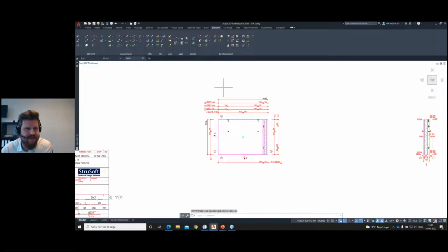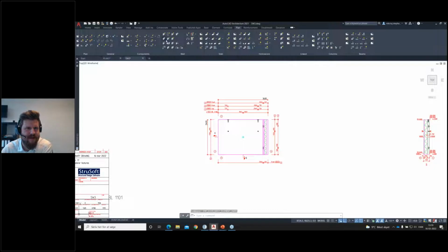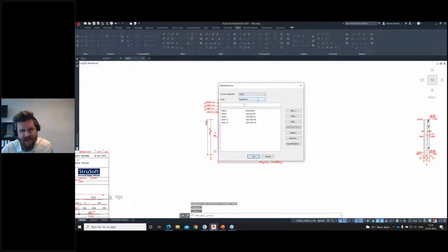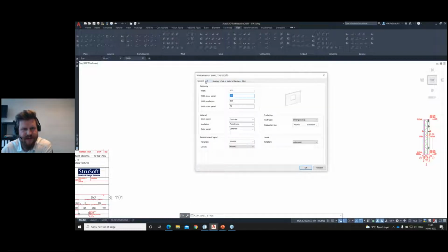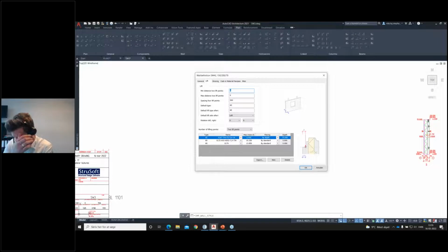If we go into the actual definition itself, the wall definition, which is what we're drawing on right now, and we look at changing it, we go into the lift settings. And here, especially for you guys who are already using the software, you'll see that this is much bigger than it usually is. And there's also a new picture. So what does this mean? Well, if we do it by standard, it's going to place the lifters in the center of gravity. We're going to do maybe some automatic thickenings or something like this. Just everything will be great.